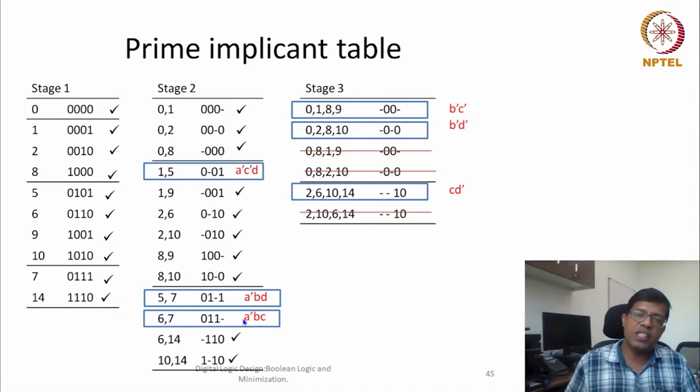So with this, our first stage is over. So the summary of this first stage, if we compare with the K-map method, is that in this method we have exhaustively searched all the implicants, and then we have exhaustively searched for our prime implicants. Because the method is systematic, we are comparing each and every term. There is no chance that we are going to miss any implicant.